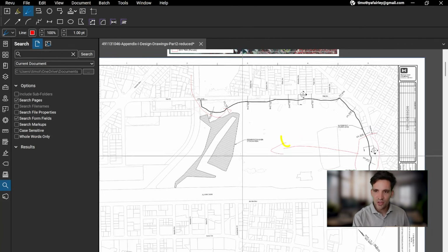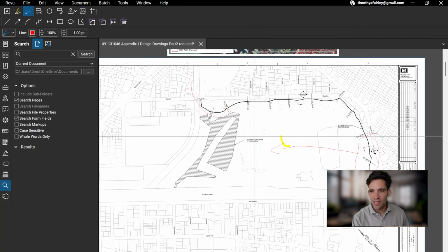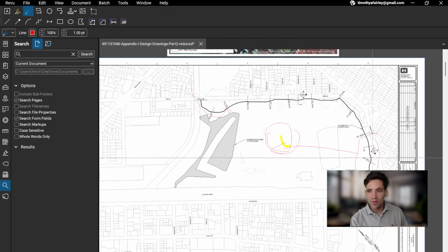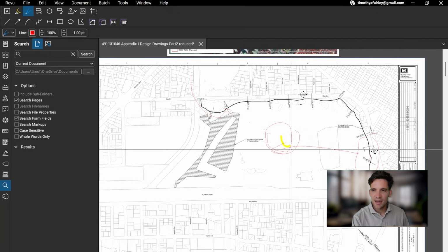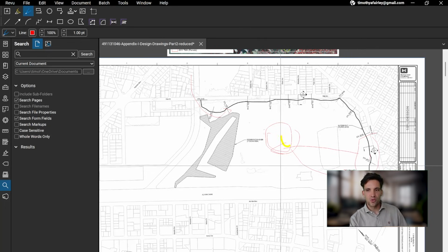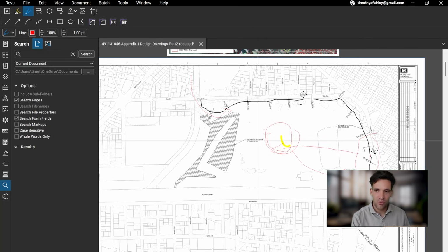Or say you start excavating here and you have a stockpile from the sediment basin, you begin excavating here, you do all the ground prep works, you could actually start placing material as you go through and do the excavation if for whatever reason you're limited in your stockpile size.